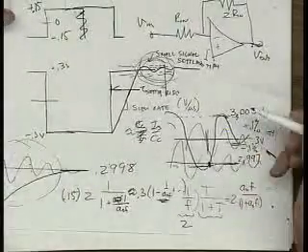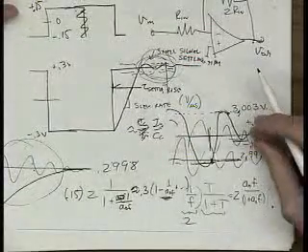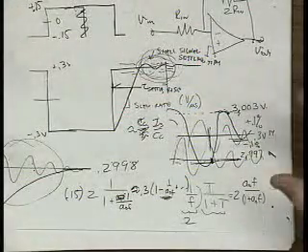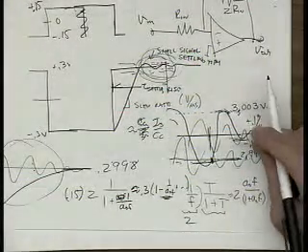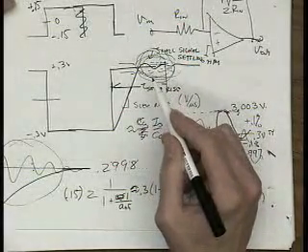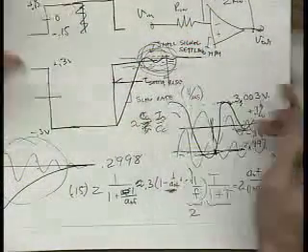So here's the point. More gain helps the static settling response, but it slows down the closed loop amplifier response. Your small signal settling time will get slower. All the time constants associated with this will get less.